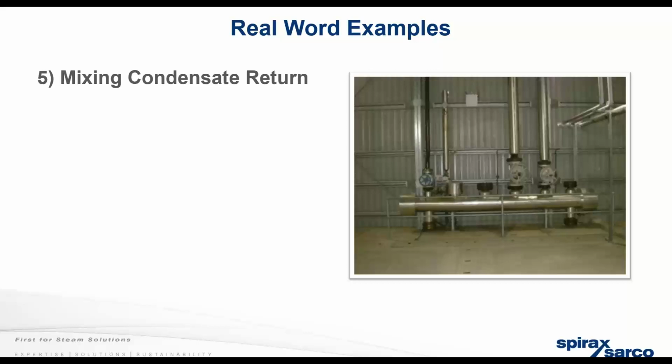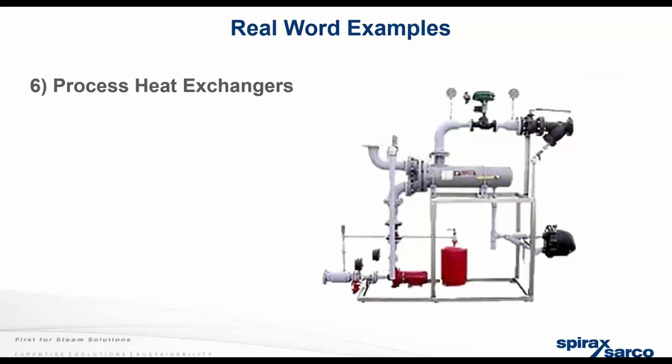If we're treating that at 0 psi steam lines, we're mixing steam, pumped condensate, and different flash. So we're getting pockets of steam that collapses and causes a real pain in the butt water hammer all the time, and for years and years and years. And like I say, it looks pretty. It's just not right because we're mixing all those different types of condensate.